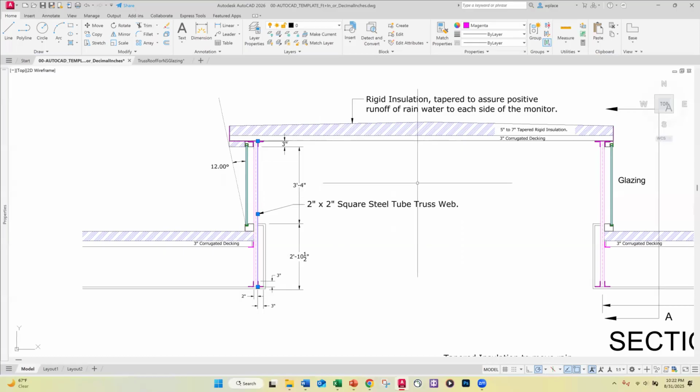And you get a direct weld connection between the walls of the two tubes. And the same happens on the outside. And so you'll get a better truss system if you do that. And it will be beautiful and clean in a way that double angle trusses tend not to be.